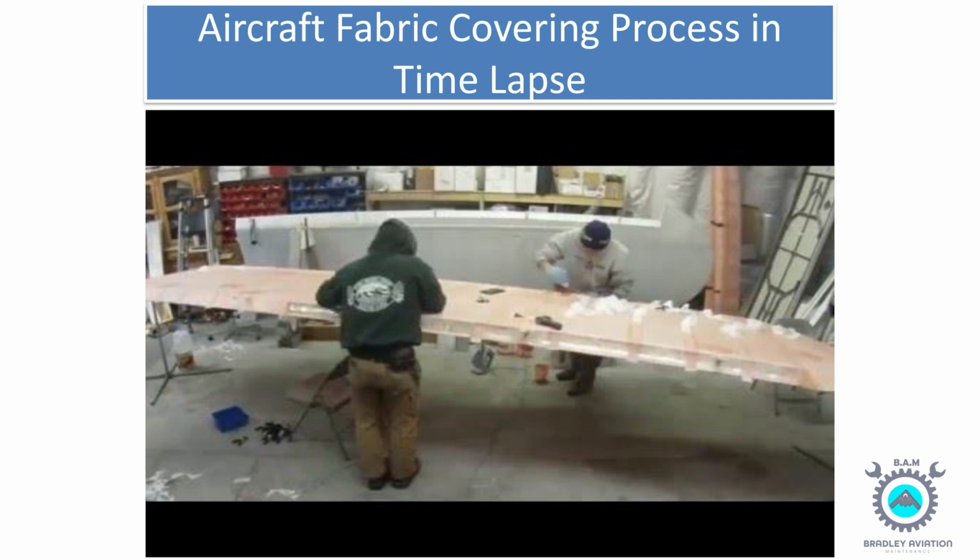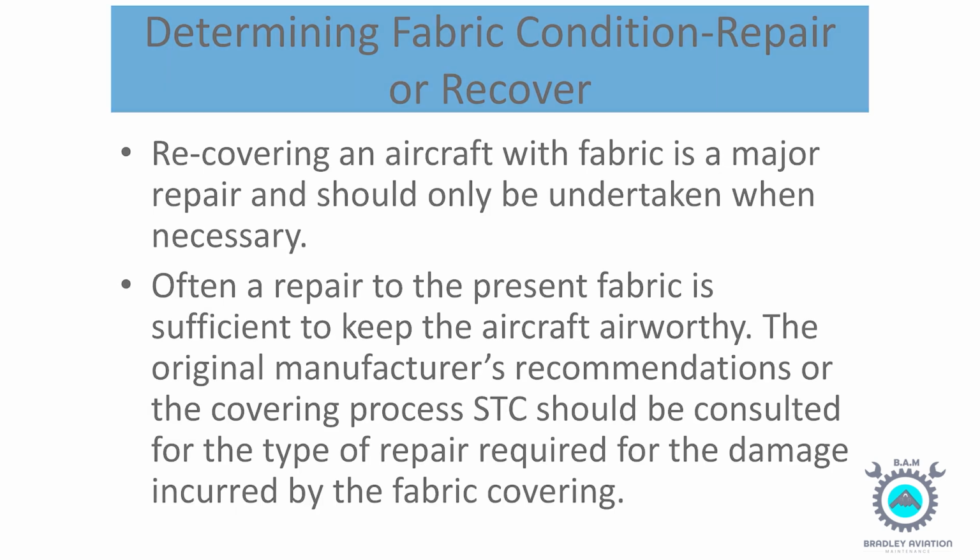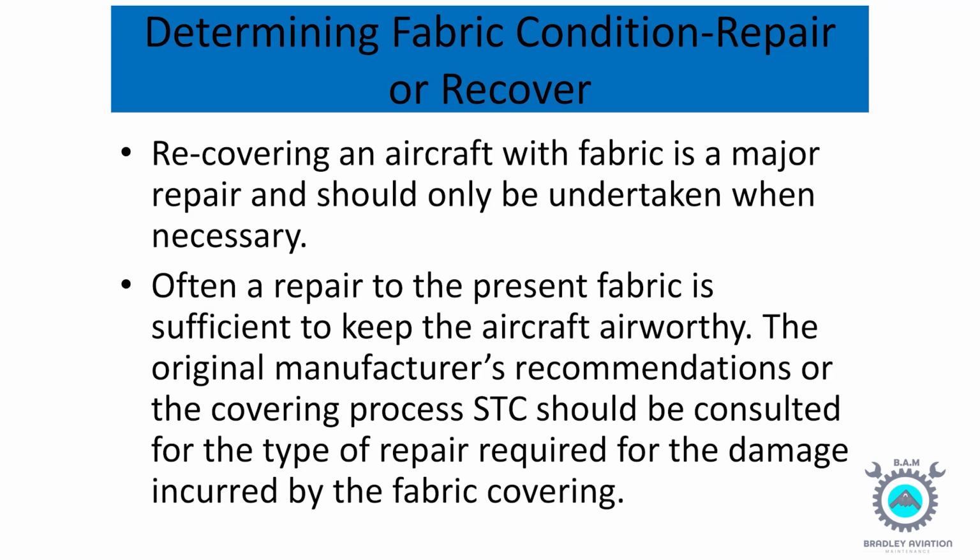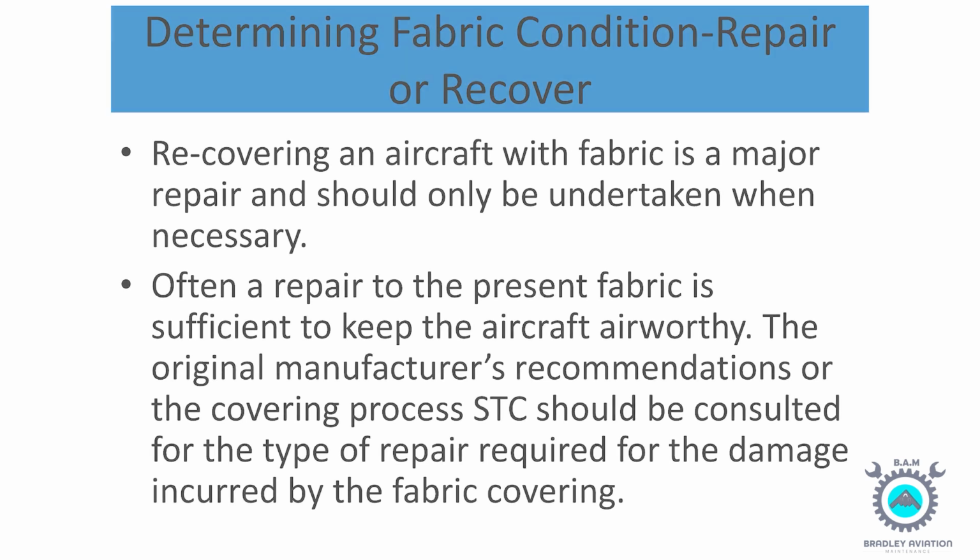Aircraft fabric covering process in time lapse. Determining fabric condition: repair or recover. Recovering an aircraft with fabric is a major repair and should only be undertaken when necessary. Often a repair to the present fabric is sufficient to keep the aircraft airworthy. The original manufacturer's recommendations or the covering process STC should be consulted for the type of repair required for the damage incurred by the fabric covering.